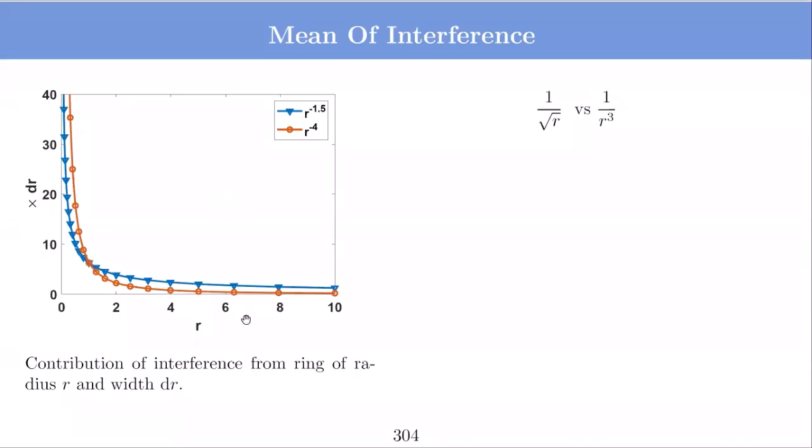But because the interference power decreases with alpha significantly, the total contribution is small. Here you see the opposite effect because of the path loss, which grows as r becomes smaller. The base stations are small in number, but their individual power is high.